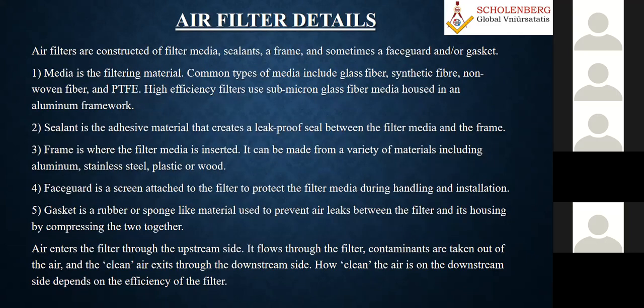Again, as I told you, particularly these air filters, generally how the air filters are constructed. Now, if I ask you how air handling units are constructed, we know that the body is constructed with a double skin. Normally you write the specification, then you have a cooling coil. Cooling coils are made with a header, and then you have copper tubes, sometimes even copper fins or aluminum fins. You normally use different kinds of material, even a micro-channelized heat exchanger. Similarly, for the air filter, you have major construction parts. Basically, you have filter media, and you have to specify what type of filter media.